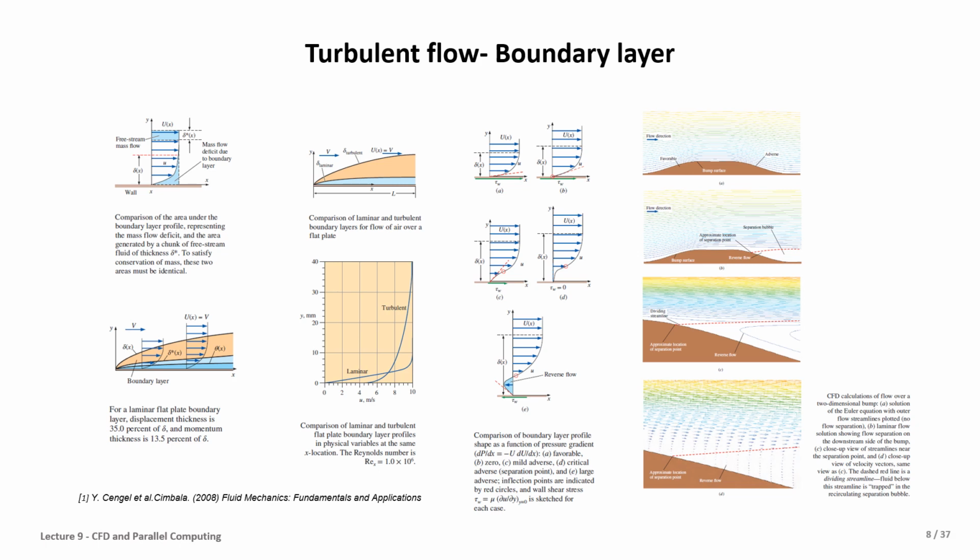a sphere or a cylinder in the air or in the water, or one of the famous examples that everyone has experienced, the aircraft when it's passing through the airflow. When the flow is passing the surface, there are some specific conditions where a separation point happens, and then there is a critical adverse pressure gradient, which makes a difference in pressure, and it's impacting the drag coefficient and drag force.